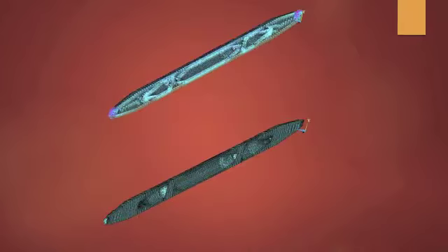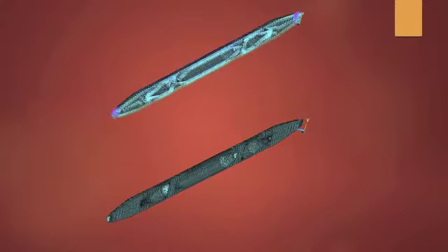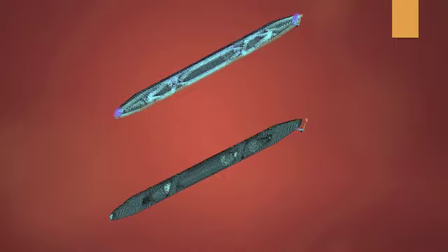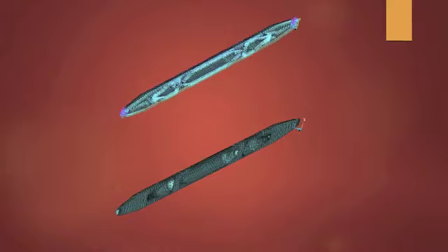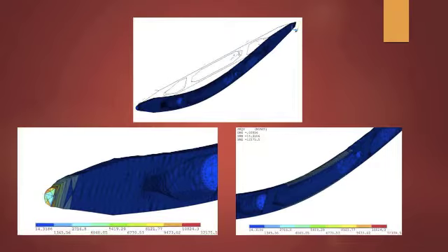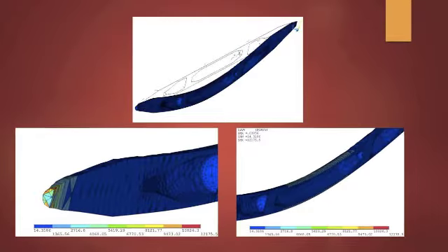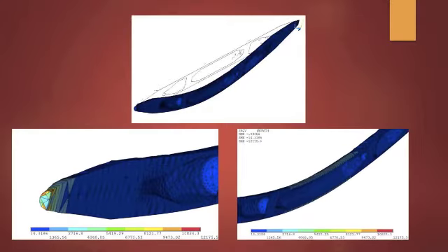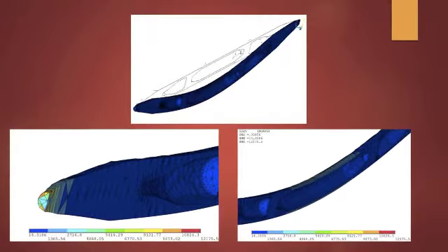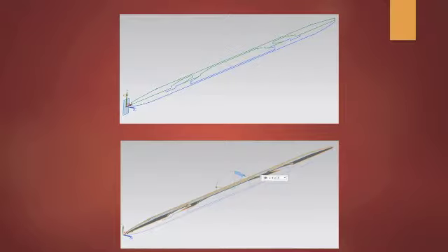In order to be able to see the results on the interior, the beam was cut in half and a symmetry boundary condition was applied on the cut face. The results of stress and displacement are good, but since we didn't match the diameters of this design and the original beam, the volume is 40% larger. For the final iteration of the design, we further scaled down the diameter so that its max is equal to the original diameter.